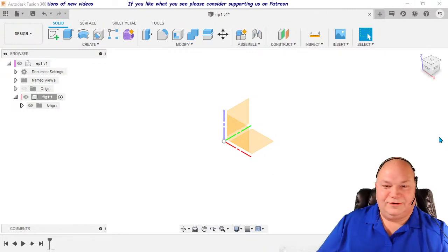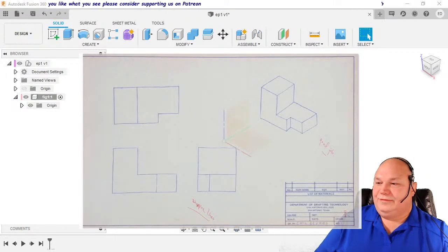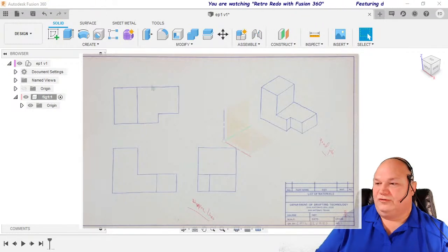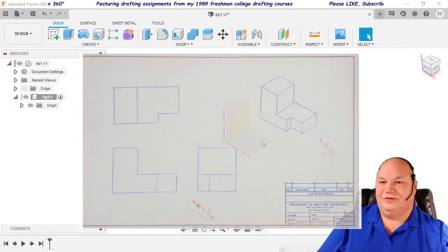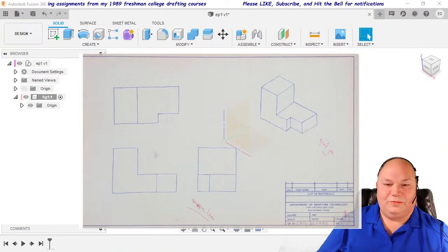So let's take a look at our object again. The way Fusion operates is that you ideally can just sketch the basic outline. So there's my cursor. You can see that, right? Can you see that cursor? Yes. All right. So you want to kind of just make this main outline first, looking down from above. And that means that we want to draw our sketch on this top plane. It's actually the bottom in this view, or will be the bottom.